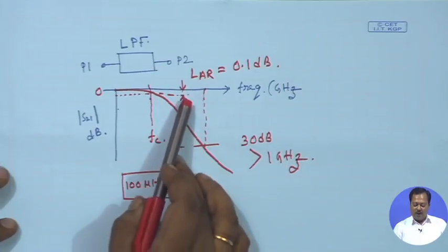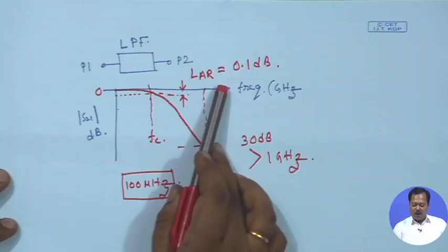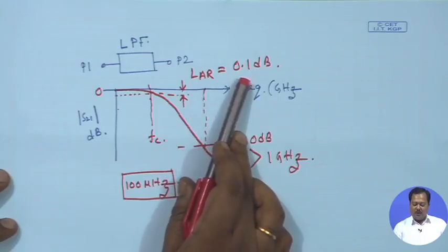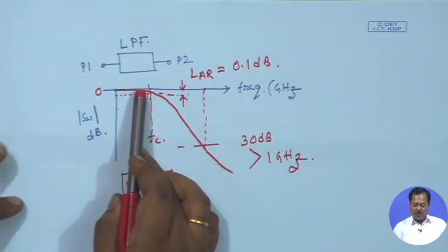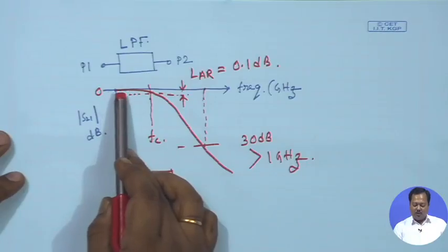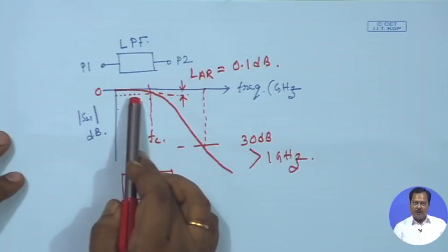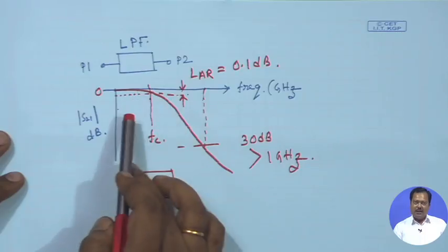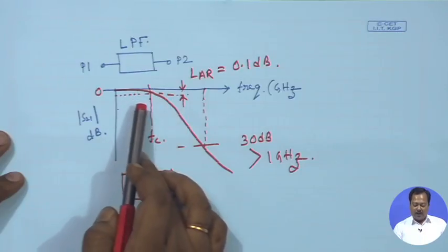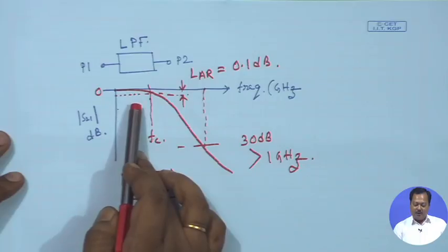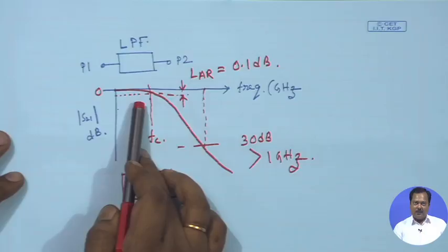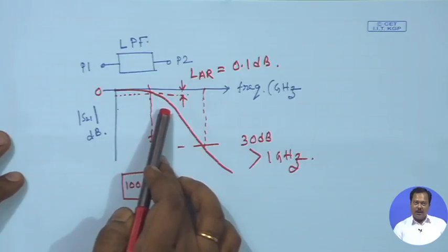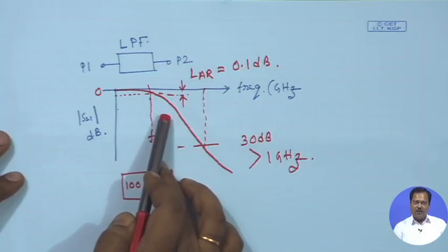Now, after fabricating this filter, whatever bandwidth I am defining, let us say 0.1 or 0.01, it can't be measured because of fabrication tolerance and also the accuracy problem of the VNA. This S21 will vary inside the passband, and this variation will be more than, let us say, 0.01 dB. That is why it is really difficult to measure the 0.1 dB or 0.01 dB bandwidth of a filter, and practically we measure 3 dB cutoff frequencies. It is easier to measure.